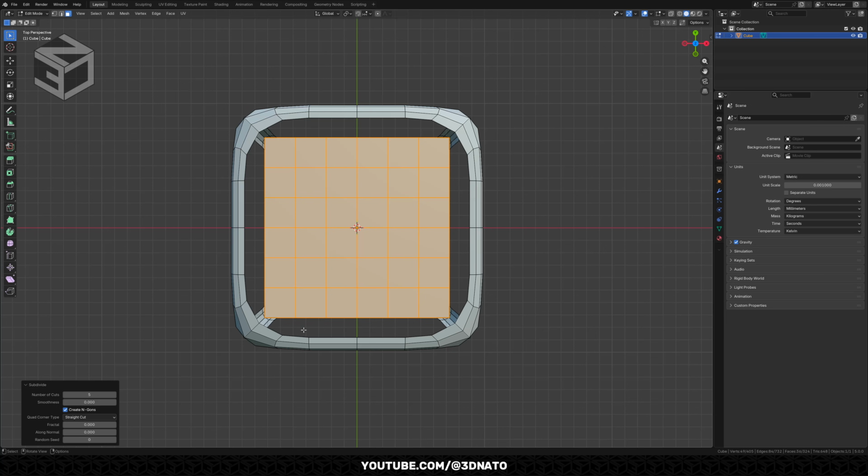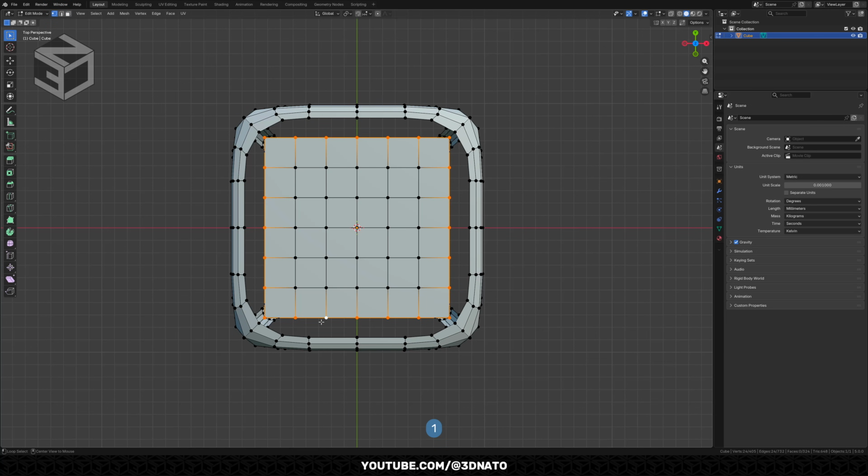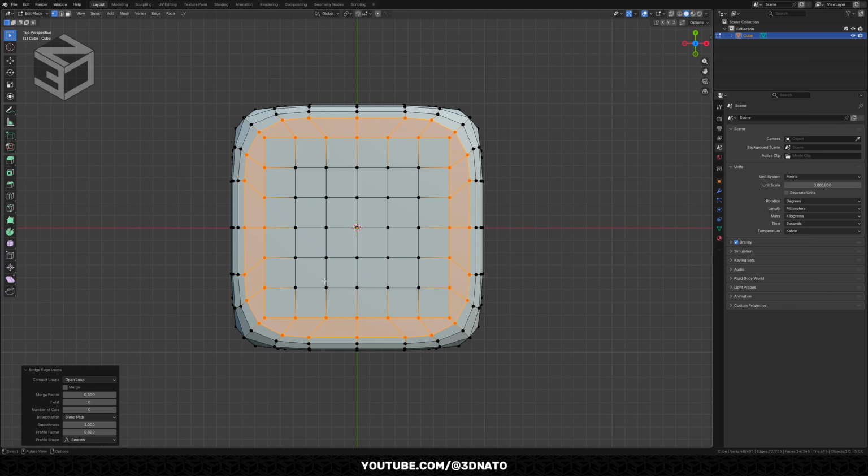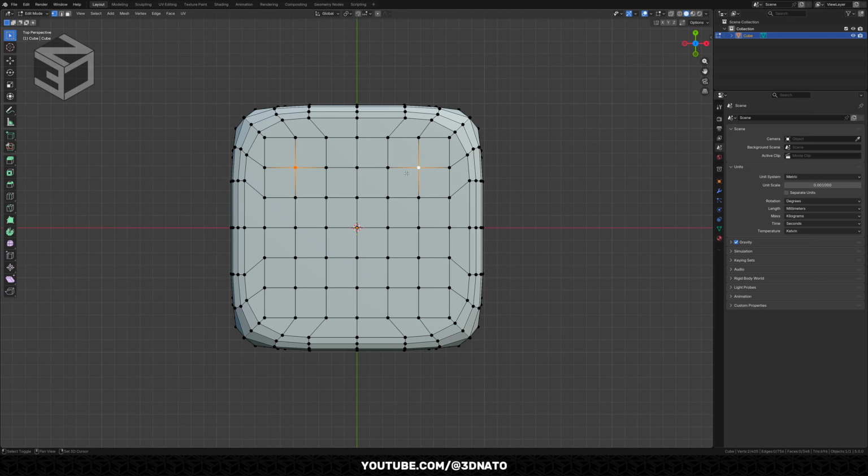To fill these faces around, let's use Bridge. Select these two edge loops and bridge edge loops to fill the gap. Here I'll create 7 circles on this plane, and with them, we'll be able to create all combinations.